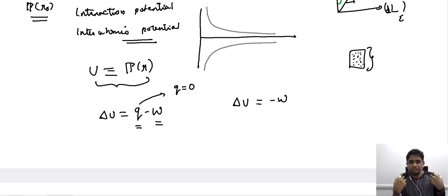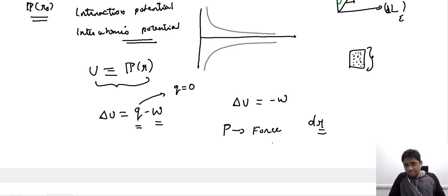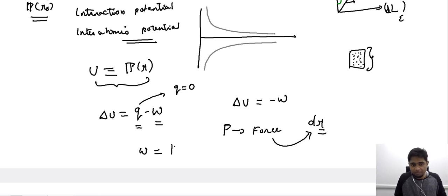When we say work, what we are essentially doing is imposing a uniaxial tensile load. The load is nothing but the force that we impose onto the system. In response to the force, there is a displacement in the positions of the atoms. R is the original position of the atom. So the work that we do on the system can be quantified as the product of the force and the change in the interatomic distances.